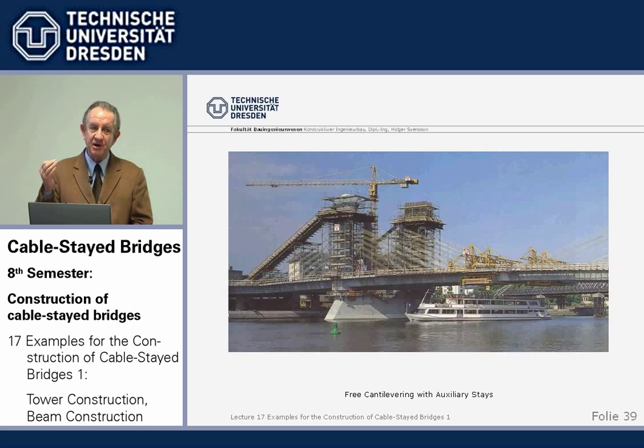And so that's why I say, when we design a bridge, not primarily for architectural reasons, but for efficiency and economy, then we must have in mind, with the first start of a soft pencil on a foolscap size paper, when we make the very first design, how do I put it together? And when we think of single, fore and backstays, there must be some, I won't say alarm, but some consideration. Hey, how can I build it? And if we go not for architecture, but for economy, we very soon find we'd rather use a greater number of stays for ease of construction.